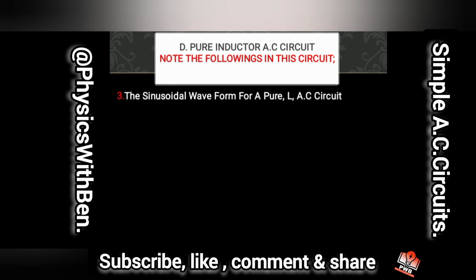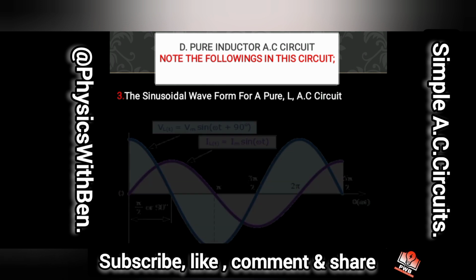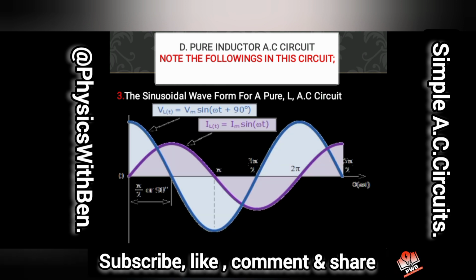Next up, the sinusoidal waveform for a pure L. L stands for inductor, and then this is it. In this case, I said the voltage will lead, and as you can see here, the voltage is leading. It attains its peak here before the current attains its peak at this point. The voltage also first attains its zero value here before the current attains its zero value here. So we can say that the voltage is leading by pi over 2 or 90 degrees, and the current is lagging by pi over 2 or 90 degrees.